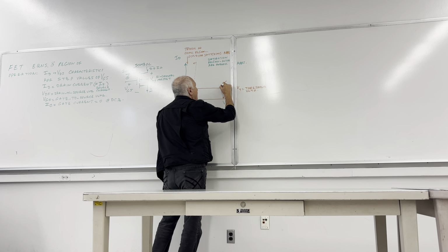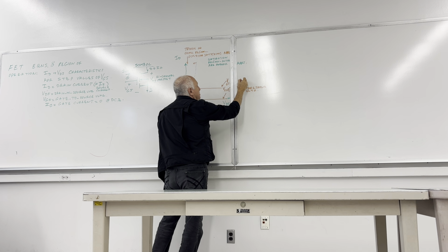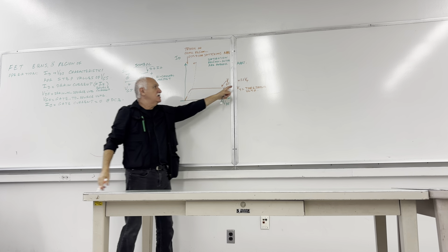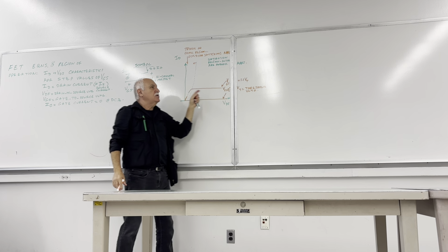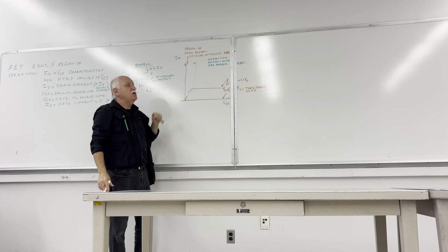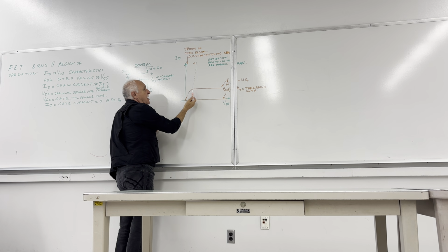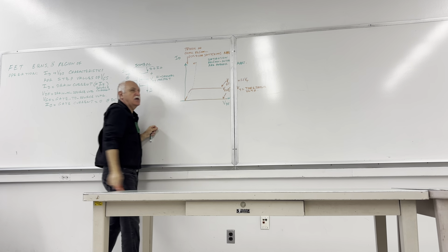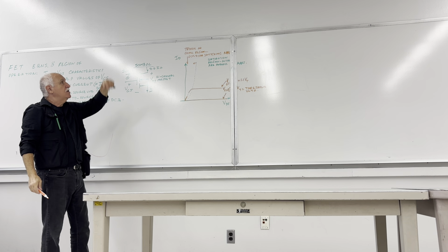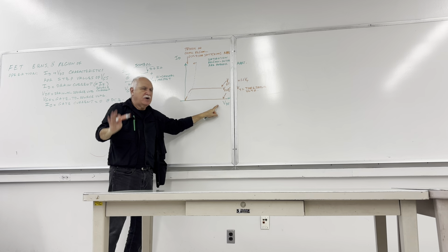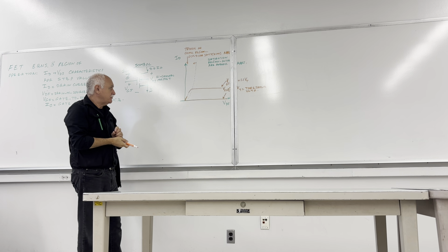For VGS, let's say equal to 1.1 times the VT, some 10% greater than the threshold voltage, we will get a constant current in the transistor. Initially it will be linear, and then it becomes a constant current. ID is a constant, theoretically independent of the VDS.